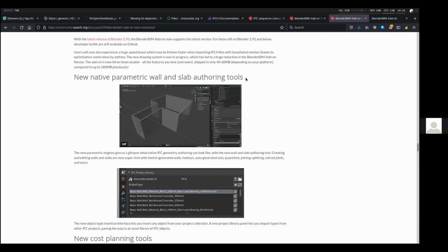First, you create the wall itself, then you create the geometry for the wall, and then you have to create the data for the wall, like its quantities. Then you might also include an axial line for that wall, so that you know where the material layers start from. So you say that the outermost layer starts here, and then it goes inner layer. And then you might also generate an extra plane for structural analysis. So there's all of these separate steps which happen when you draw a single wall.